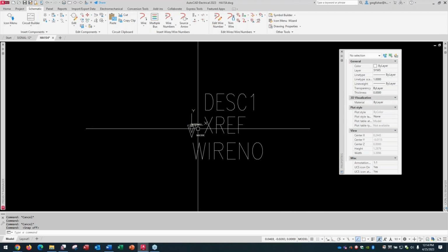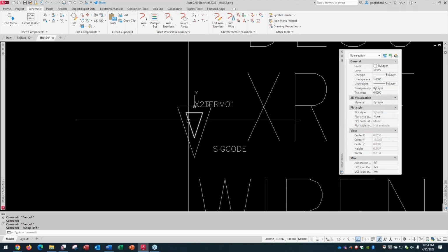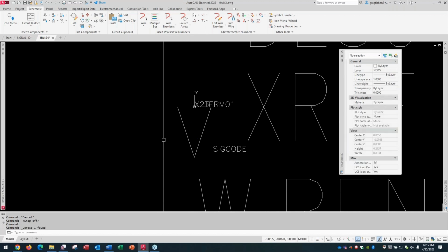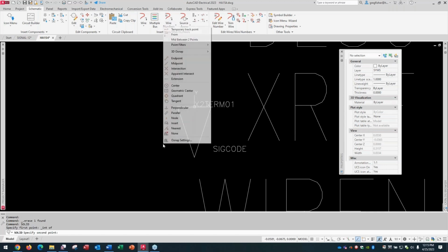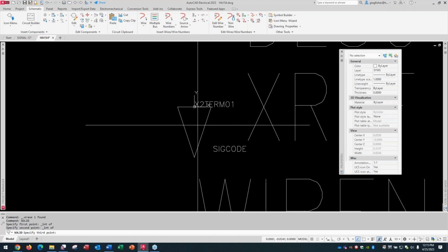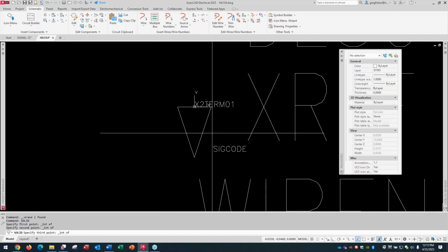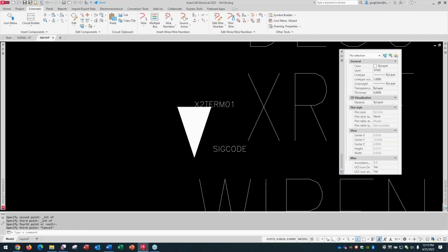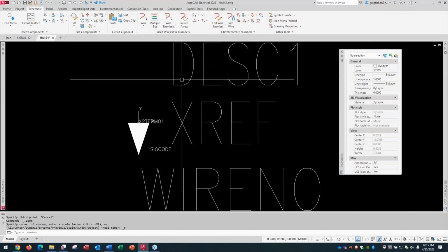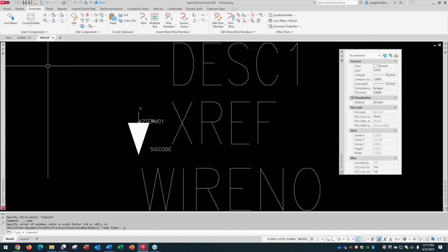Now, in this case, just to save some time, all I'm going to do is put a solid in the arrow. So the regular AutoCAD solid command. And I'll say, let's go from the intersection here to the intersection here to the intersection here. So I changed something, just so you can see that I changed something. And then I'll do a zoom extents again. I could have changed a lot more. And then I'm just going to save and close this particular symbol down.